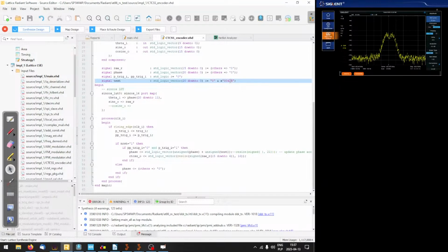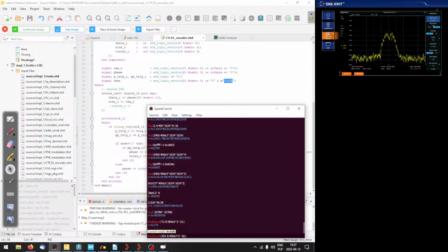So the value that we have used here was for 127.3. That was the value that we have used previously. So now the radio, the OpenHT, transmits a 127.3 hertz tone. And in the radio, I have actually used that exact value, 127.3. Yeah, it matches. And there's the beep.